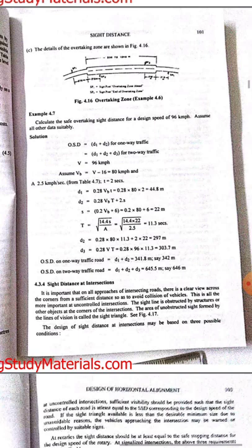So there is a formula for overtaking speed. If the overtaking speed is not given, then we take it from the overtaken vehicle speed, that is Vb equal to V minus 16, that is 80 km per hour. Why do we use the V minus 16 equation? Because V is in kilometer per hour. So 96 km per hour, and we use the equation Vb equal to V minus 16, that is 80 km per hour, and a is equal to 2.5 km per hour per second, t equal to 2 seconds.